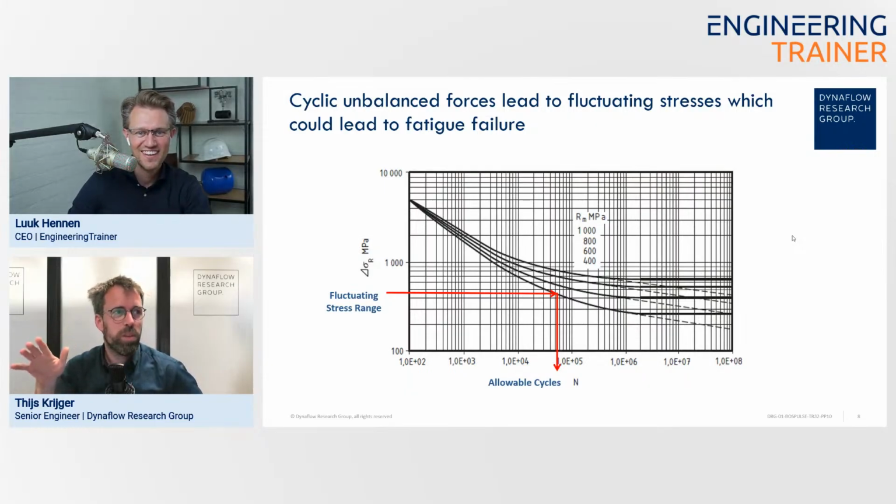I wouldn't be too sure, but if the system's been running for a couple of years and it hasn't suffered any fatigue damage, then still, good practice and good hygiene to increase the integrity of your system. But conceptually, you almost have to be safe compared to the fatigue limit.